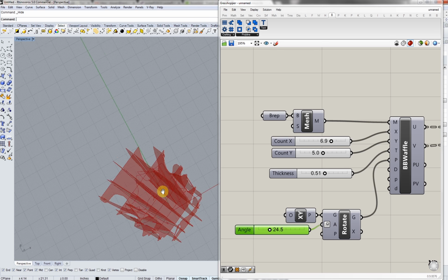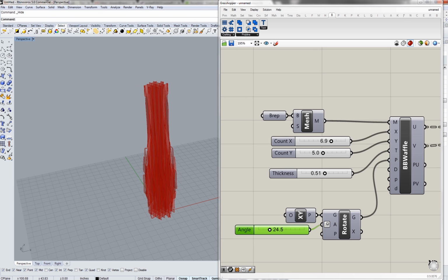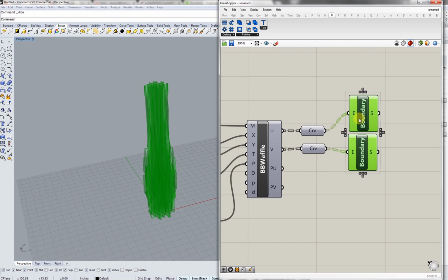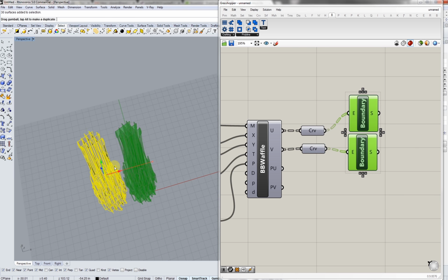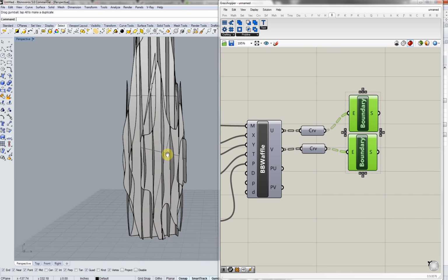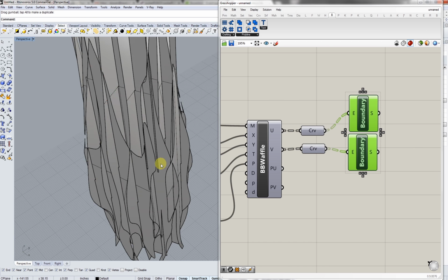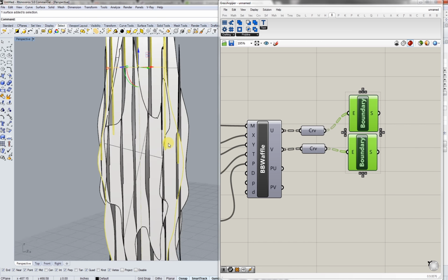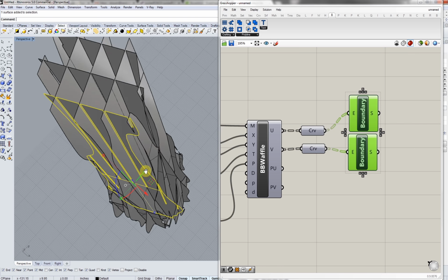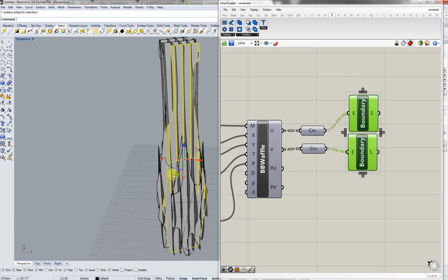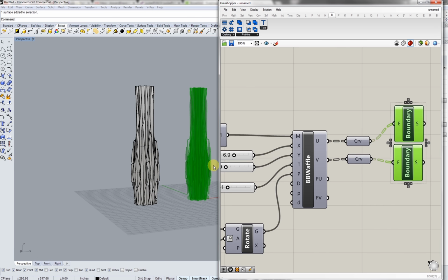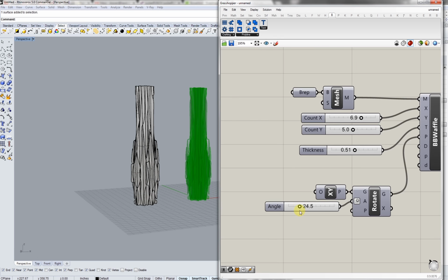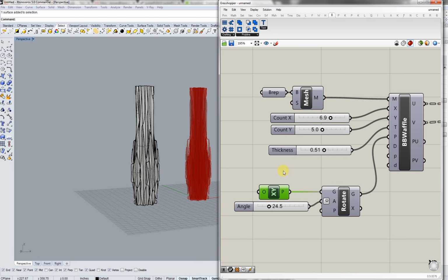So now, let's say we want to increase our slices. We're able to do that just with the number sliders. All the notches are updated. Now I'm going to turn these guys and bake them just to show you a version of the waffles that we just created in Grasshopper. It's pretty interesting kind of forms, and the notches are already set to the midpoints, so it's ready for fabrication. So this is a lot better than spending hours and hours trying to figure out your center points.